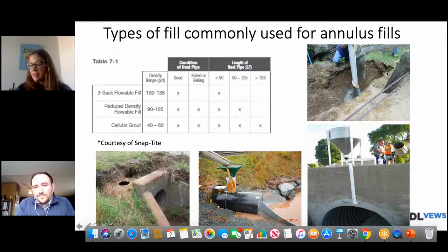Okay, and then this leads right into the next question of how do you manage grout pressures to prevent collapsing of the liner pipes? Do you want to dig more slides before we talk about that? I think, definitely, please bring it back up, though. It's certainly something where, as you know, we could probably have an hour conversation, and I don't want to submerge this conversation in that. I would boil it all down to one statement, and that's always talk to your lining manufacturer and ask them, where do those pressures come from? What do I have to watch out for? And ask that person to help you out in figuring out where those pressures could come from. That's the one generic comment I'll say.